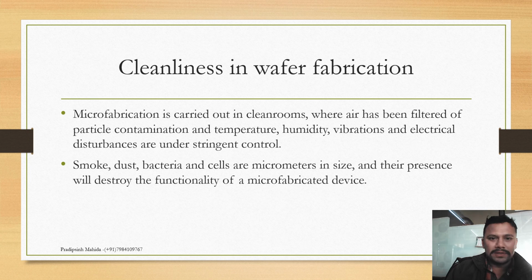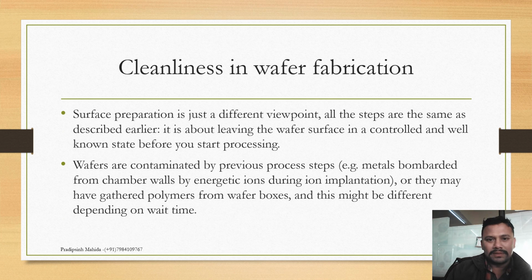Cleanliness in microfabrication. Microfabrication is carried out in clean rooms where the air has been filtered of particle contamination, and temperature, humidity, vibration, and electrical disturbances are under stringent control. Smoke, dust, bacteria, and cells are micrometer size, and their presence will destroy the functionality of the microfabricated devices.